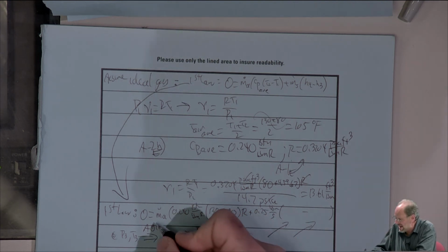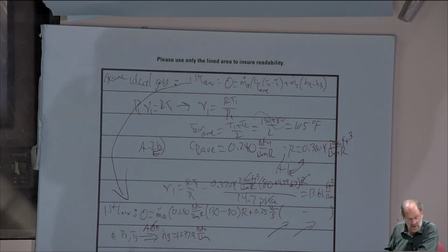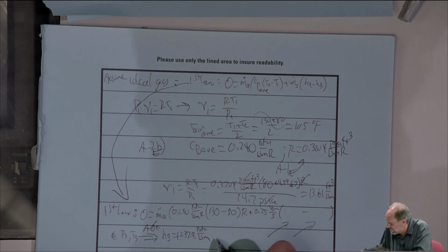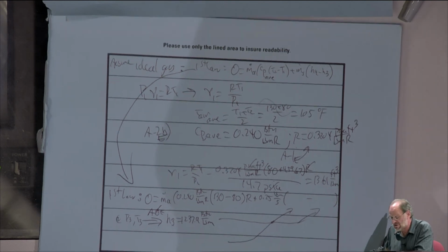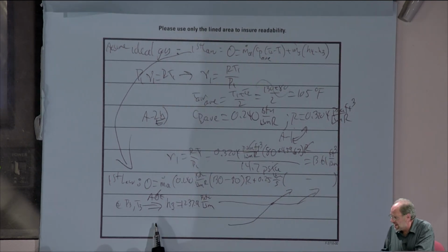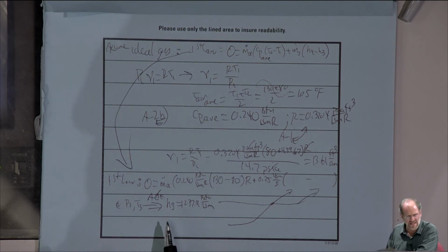Now again, take the test if you need to. Certainly it could be shown that the given temperature is greater than the saturation temperature at 30 psia, which is your given pressure, so it's clearly superheated. But what about point 4? Well, let's see. I'm not going to assume that it's superheated, and in fact, it isn't, is it? You should be able to see that just by looking at the given data.